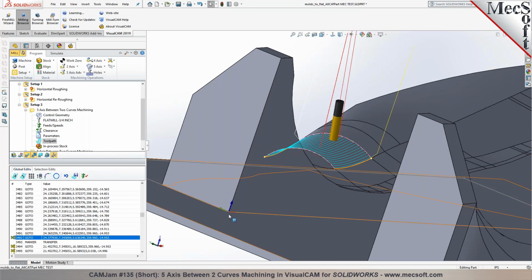So you probably would be touching off at one of these points and establishing your origin. So the C and B angles are computed based off your 0, 0 initial position that you set. Okay. So what you're saying is, C0 is aligned with the x-axis or the c-axis?